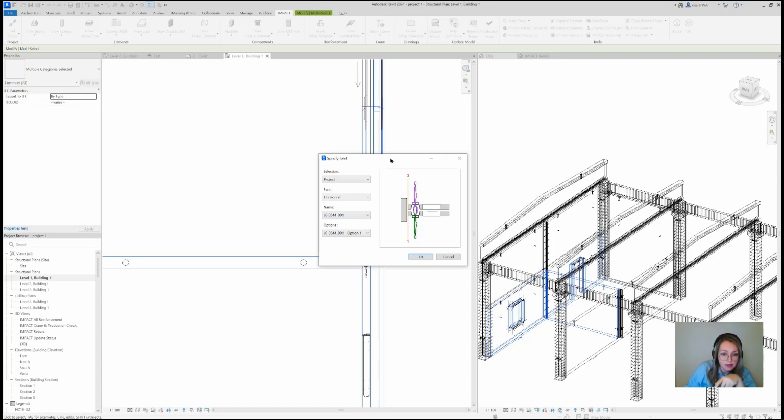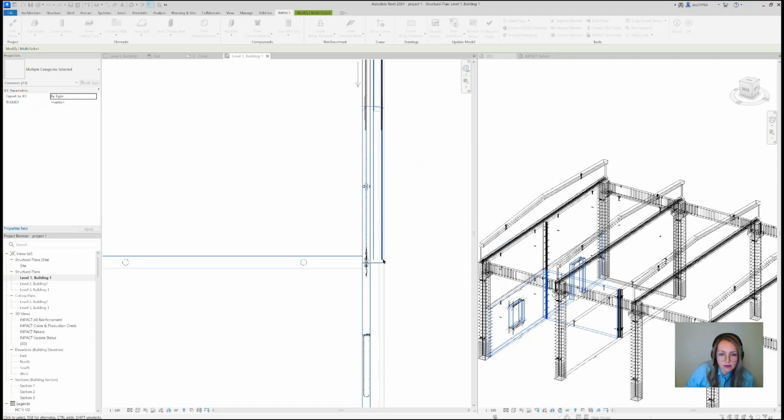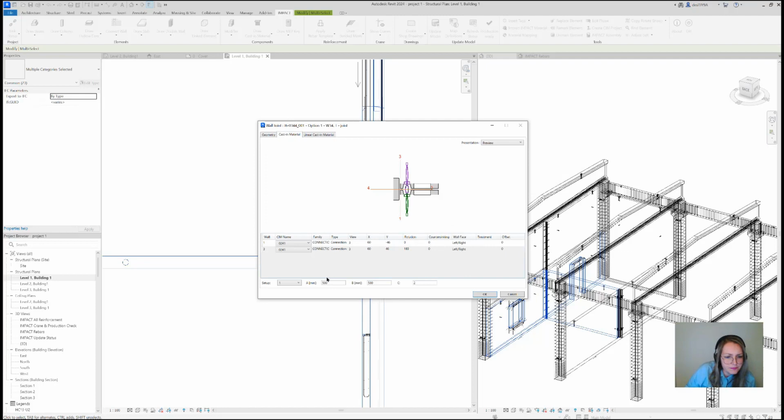So in this case, you can see my wall is joining the sandwich walls. I need some space, so I'm just going to choose this one where I need to see here how do we add the casting materials. If you go to placing, I have two casting materials, 500 from top and bottom.